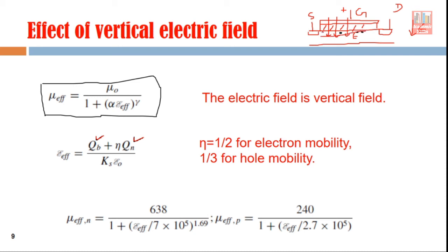Near the source the depth of free carriers is more, meaning they are distributed to a long depth, but if we go near the drain the depth becomes less, and sometimes the depth is zero because the free carriers are not present near the drain part, right? So that distribution is taken into account by this component, and the type of carriers, whether electrons or holes are present in the channel, is also taken into account by this parameter.